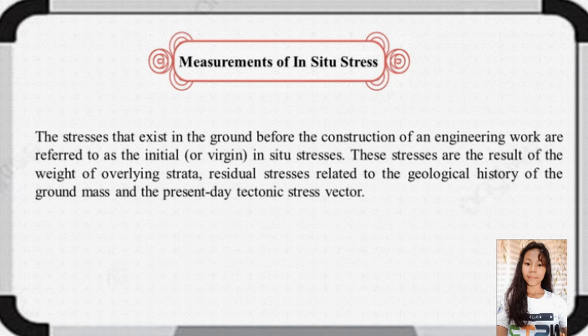Hi everyone, I am Dela Peña and I will start my discussion from measurements of in situ stress. The stresses that exist in the ground before the construction of an engineering work are referred to as the initial or virgin in situ stresses. These stresses are the result of the weight of overlying strata, residual stresses related to the geological history of the ground mass, and the present-day tectonic stress vector.